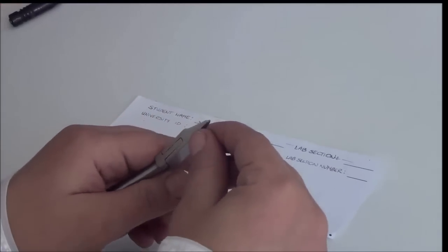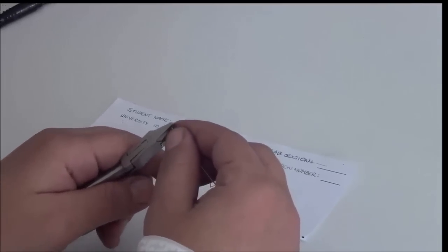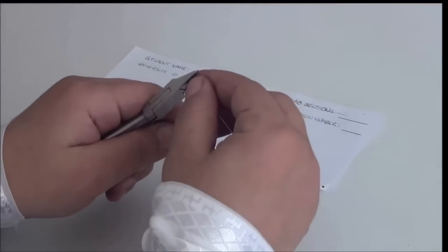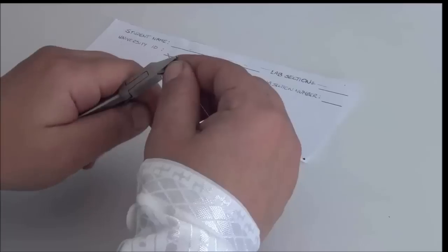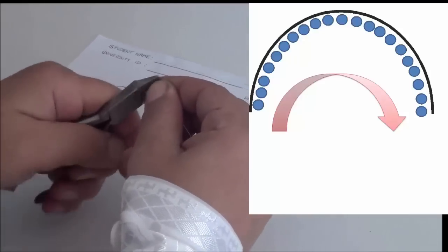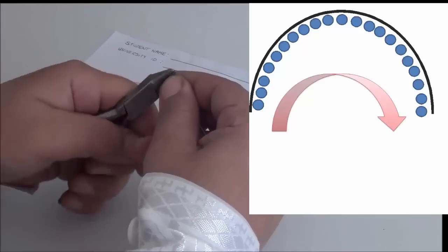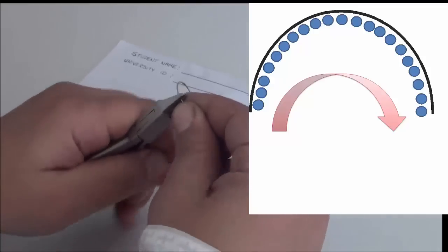The wire is at 90 degrees with the pliers. I use my finger to begin bending. But actually I do not make a complete bend. I just bend slowly in a slight amount. I move a bit and bend, move a bit and bend, move a bit and bend. This bending creates the curve.